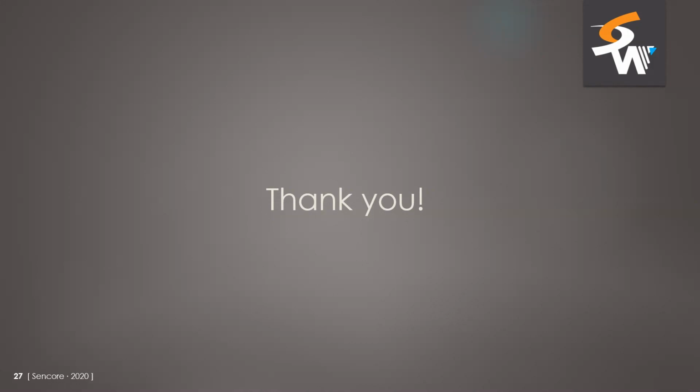Another question back to the SCP is, can you talk about ancillary data support from the SDI input? Yeah, absolutely. So from the get-go here, we're obviously going to have closed caption support. I have SCTE 104, obviously translating that to 35. I have that support slated for the next release here. And AFD, I don't have that on the roadmap yet, but it is on my radar. And then I'm not sure what other SDI stuff we would want, but maybe some VITC or VANC timing or things like that.